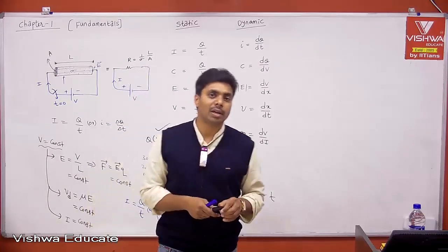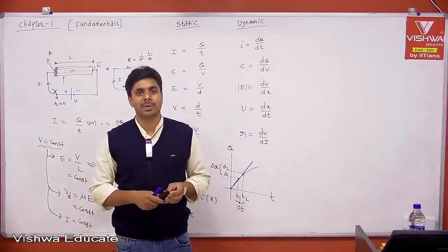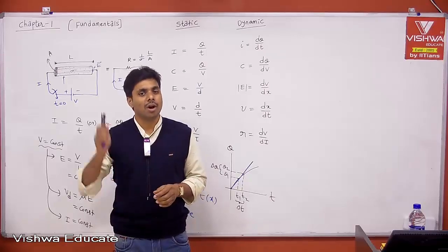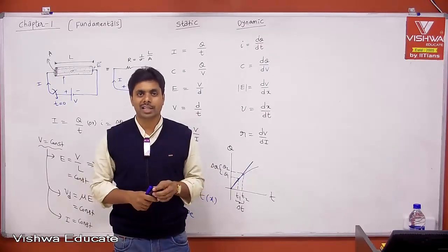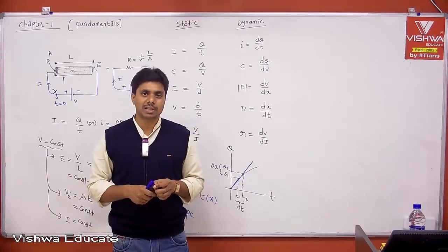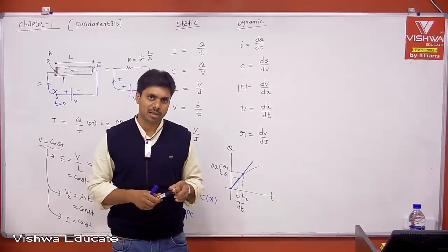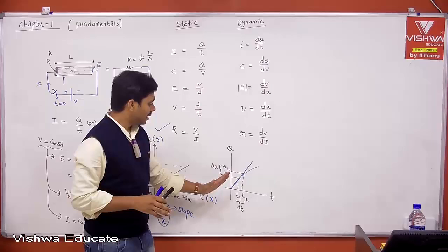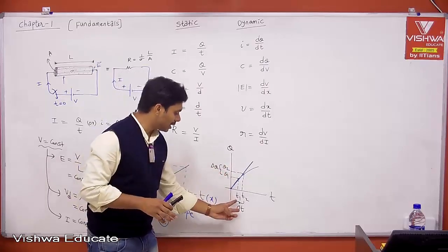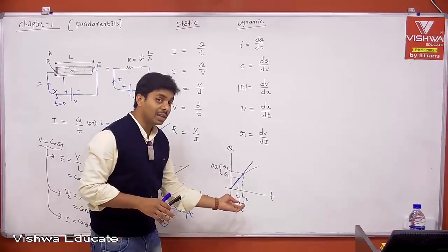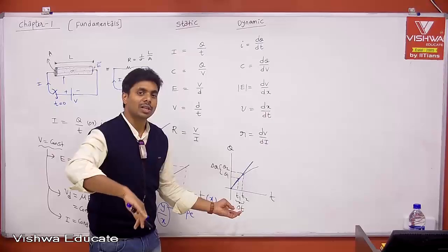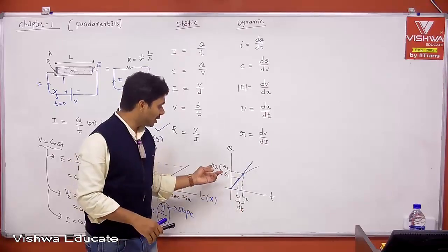I'm going to use this point later on when I explain DC analysis or AC analysis of BJT amplifiers, which I already explained a little bit in the introduction class. Here, the incremental changes are delta V naught by delta Vi, output voltage change divided by input voltage change, which is the voltage gain.